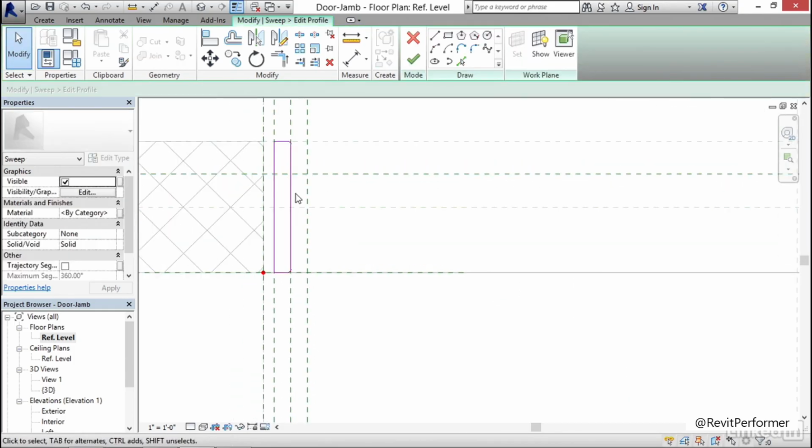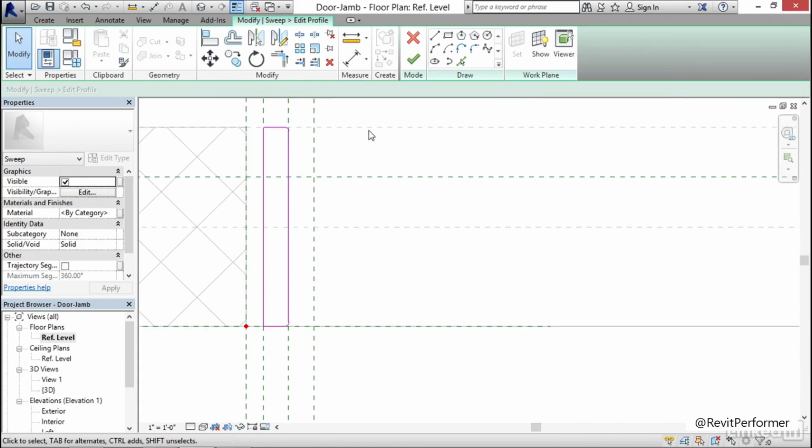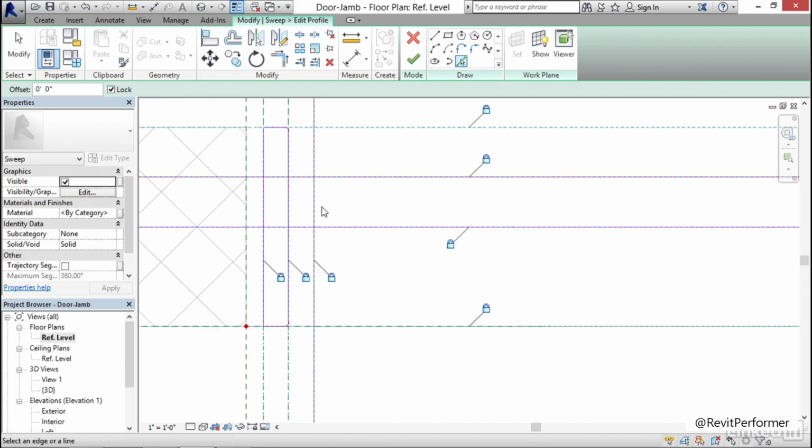Awesome. Okay, our stop is going to go right here. So on my drop panel, I'm going to click on pick lines. I'm going to make sure I lock them. I'm going to go bing, bing, bing. Hit escape. Now, let's click on our fillet arc button. Click radius. Let's put a nice little fillet arc radius here.